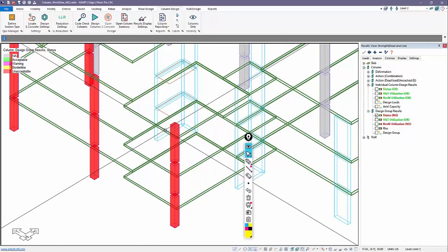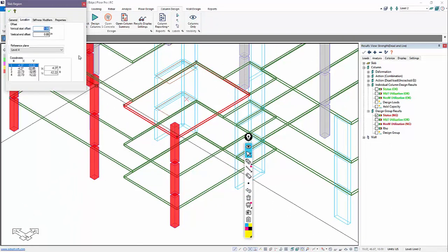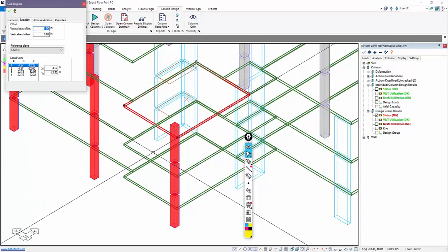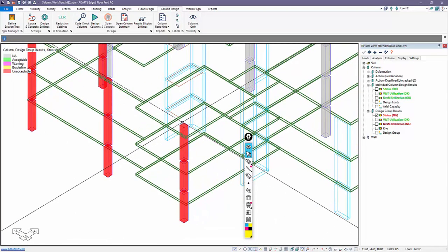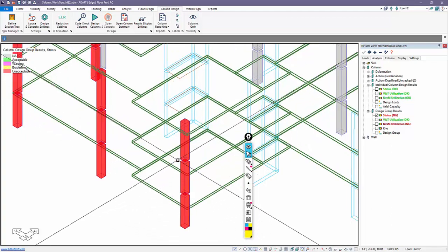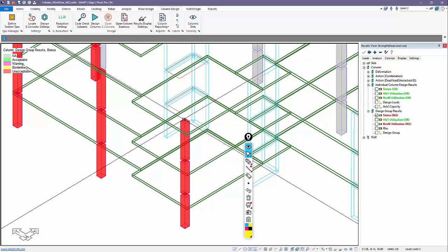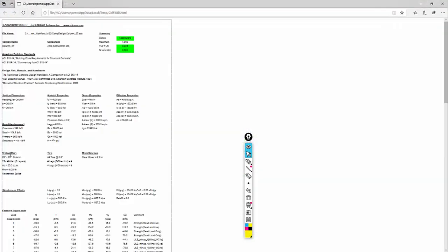If we look at the balcony slab, we'll call it, this slab is actually offset by 1 inch. So we have adjacent non-nested slabs that are offset. And because of that, the program essentially triggers this issue with the unbraced length. So if we look at this first column in sequence where the offset slab connects to the column in the stack, and I look at the summary for this column, we can see that this is what's causing the 360-inch unbraced length.